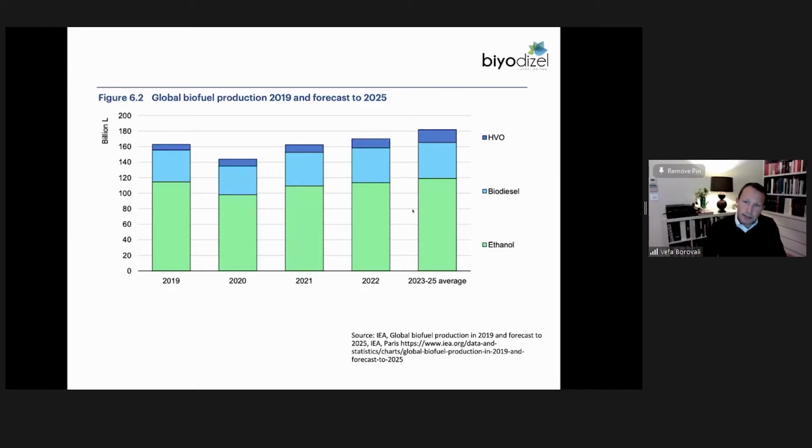The reason why biodiesel is shifting to HVO is there is a blending wall, let's say, up to about 10% blending by volume. Biodiesel being blended to diesel fuel starts to have some, how to say, technical difficulties. So, the moment we switch to HVO, there is no ceiling, there is no limit. We can use it as a drop-in fuel. It can be up to 100%, just like the aviation fuel.